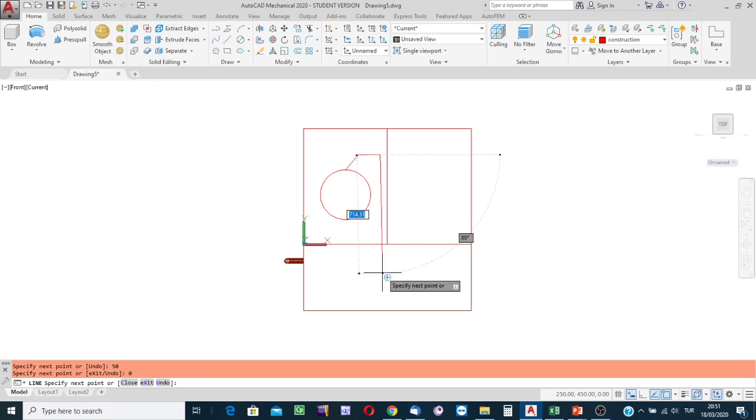So have such a further extension. Have the line further extended. Say that the length of the line is 800. Clicked on tab key and then angle. Here be careful. The angle you see from the simulated arc has to be written as measured in the clockwise direction.